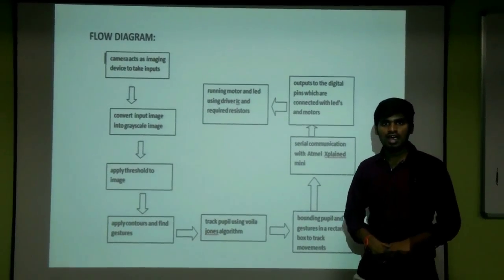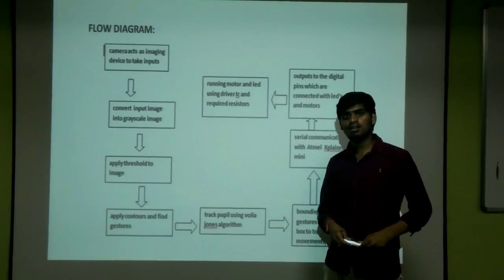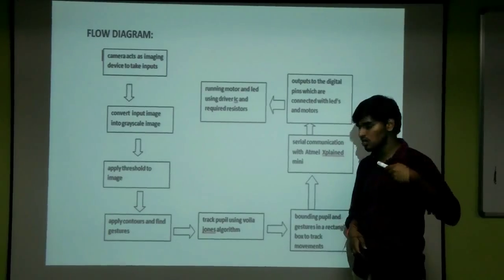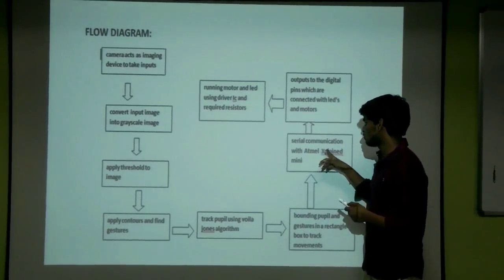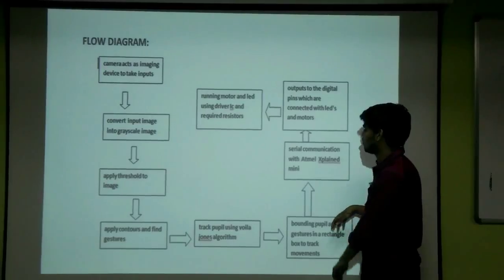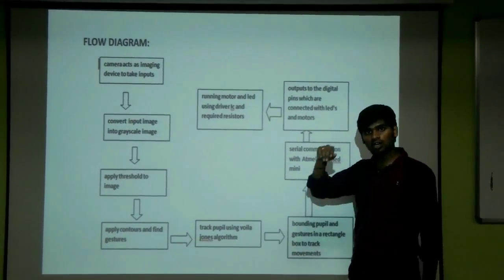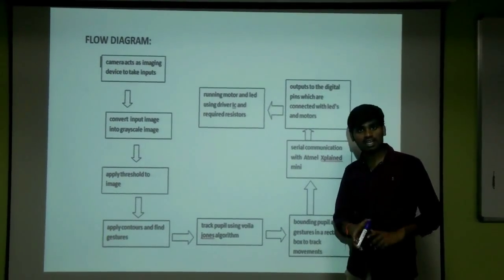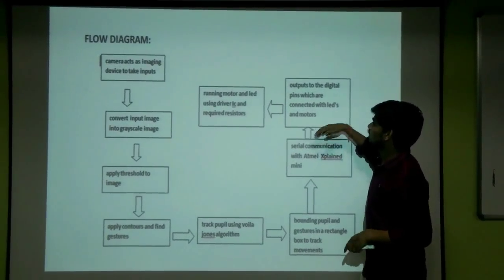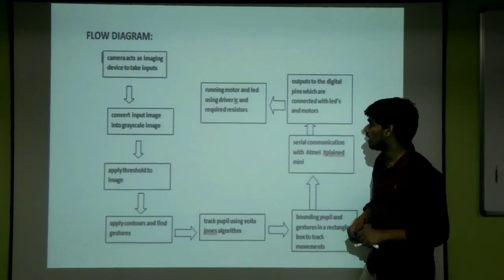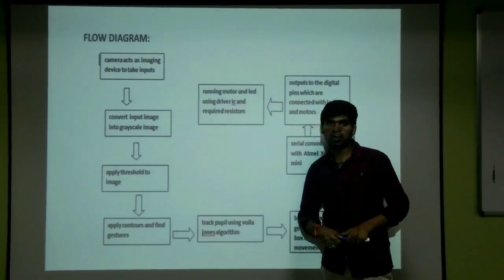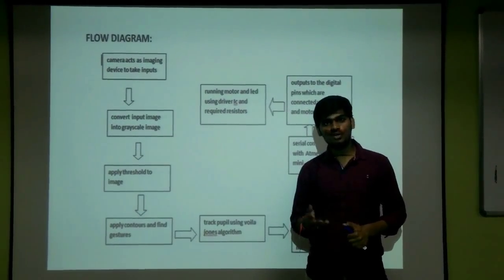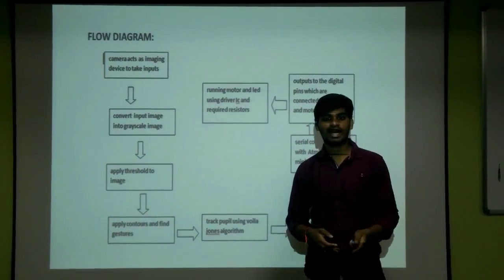After that, based on the output of this, we will be connecting to the Atmega 168PV board using serial communication, and this is done using a module called PySerial. PySerial is a module which sends data to the COM ports from Python, the third party application, to the Atmel Studio 7, which is used by the Atmega 168PV board. Based on the output of the hand gestures and the eye gestures, the serial communication is done with the Atmel board, and based on this, the respective output pins are switched high and the respective motors and LEDs are driven. And in this way, the patient or the user can use hand gestures or eye gestures to satisfy his needs.